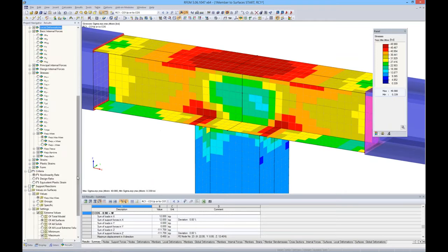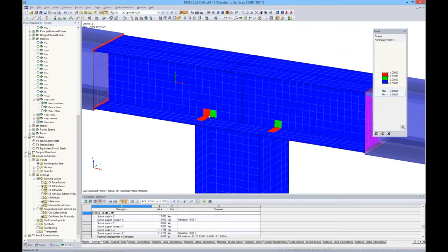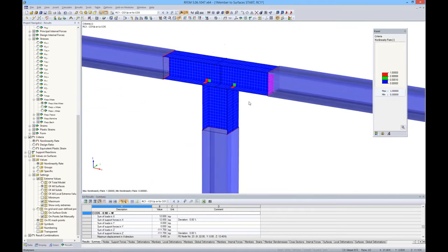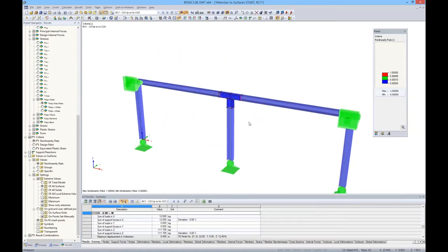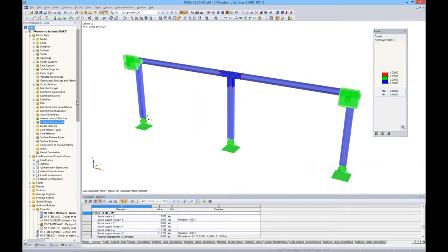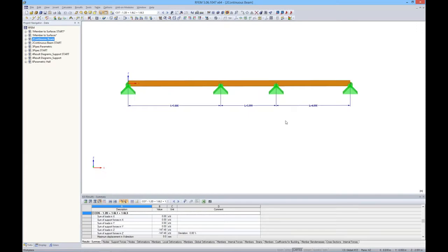I think an important thing to show you here is that we have an option under results called criteria. And this criteria will actually show us our FE elements that are in their full plastic state at 1.0. These other 2 green ones are obviously somewhere in between 0 and 1 as the ratio, and then the other elements have not reached that state yet. So that simply concludes our first example. I want to go ahead and move on to our next one, which again is very simple.